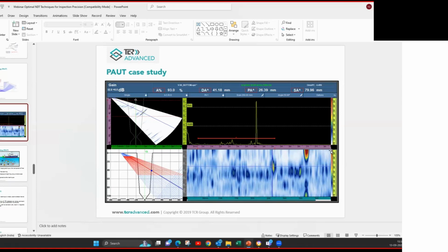Thank you so much for the information. Here we have received another question. What is the best method to check the most correct result for pipe thickness under insulation in online mode? So yes, this we have not covered, but pulse eddy current testing is available for this technology. We can identify the thickness with pulse eddy current testing without removal of the insulation.